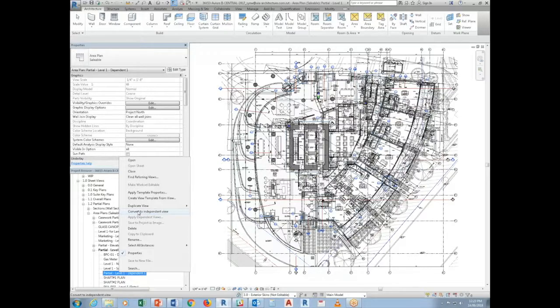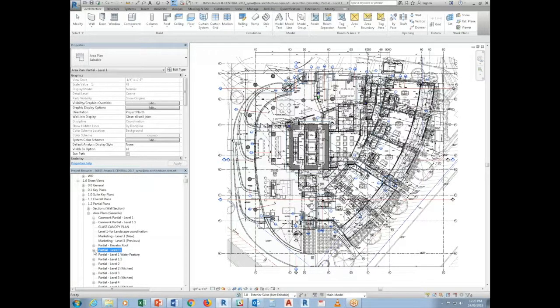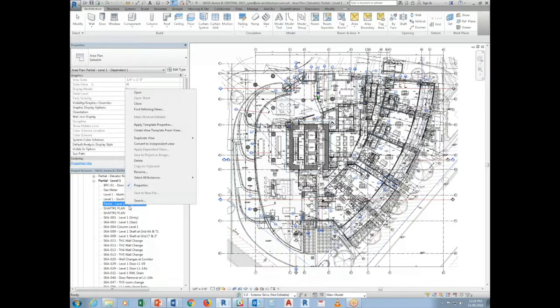Well, okay. The advantage of dependent views is that you're basically creating a view, like a subsection of this. And the other thing is that you're keeping track of what's been done to this view. In here, what I did is that I keep record of all my SKs. So you have a record stamp saying that level 1 is going to have all this SK made into this. So this is all SK for the site instruction, and then the rest is like, you got shaft plans. This one is the dependent, you can delete them.